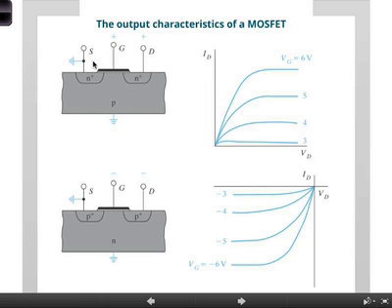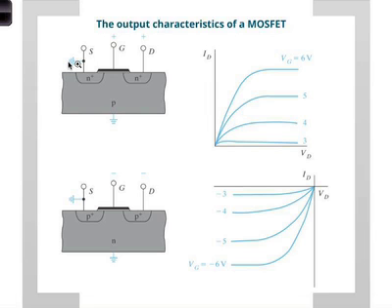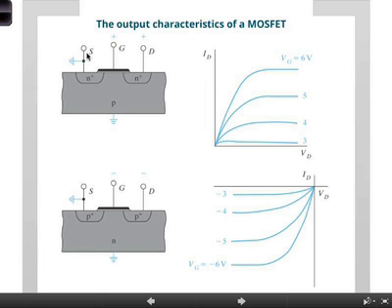Okay, we'll be very clear about this, but first of all, the source and drain are a little bit arbitrary because they're symmetric. These devices are completely symmetric, right? As long as they're free-floating. As long as I connect my source to my body, the substrate, I break that symmetry, then I know which one's source, which one's drain. But if I don't ground that, look at that picture for a second. If I don't ground that, I can't tell which one's source, which one's drain, right? Okay. The reason this is source is because this is connected to this. They're both grounded, essentially. Okay, first of all, keep that in mind.